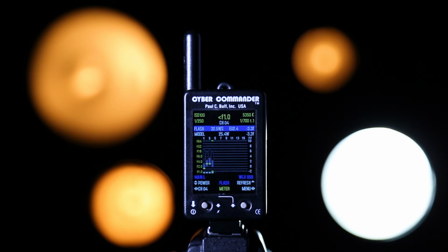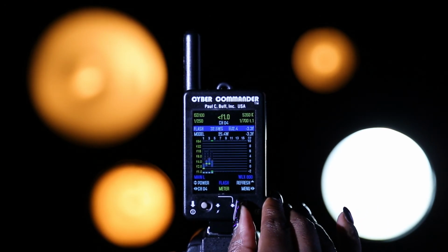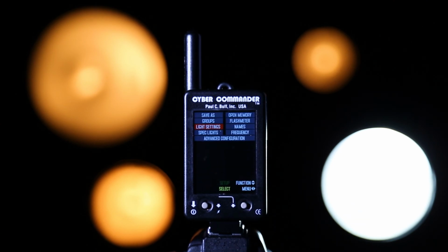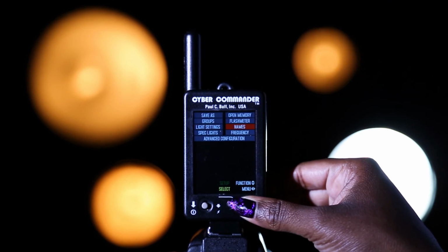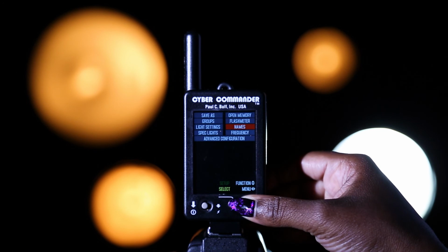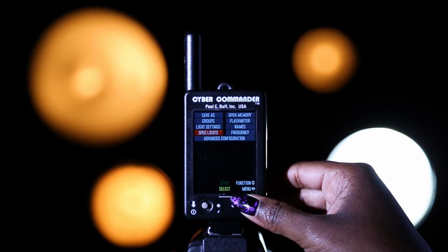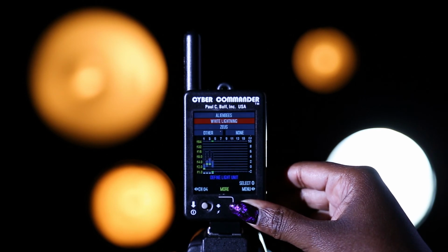One other thing I'd like to talk to you about in this video is we're going to take the right joystick and we're just going to toggle back to the setup menu. And I'd like to just show you how you can remove lights from an existing setup if you maybe accidentally added a light or maybe added a light to the wrong channel. There's a really easy way to fix that. So we'll just take the right joystick and we're just going to toggle down to spec lights. We'll just select that by pressing in on the right joystick.